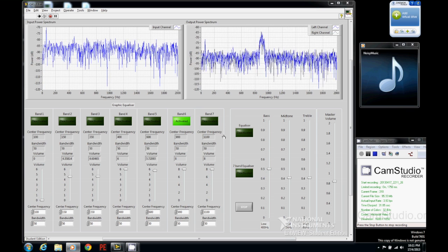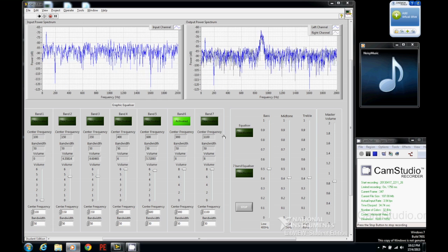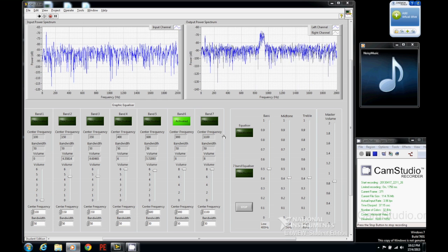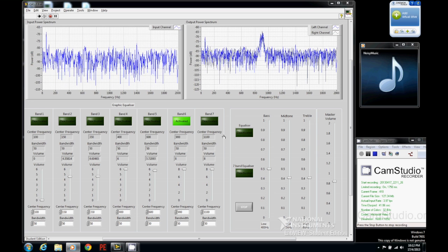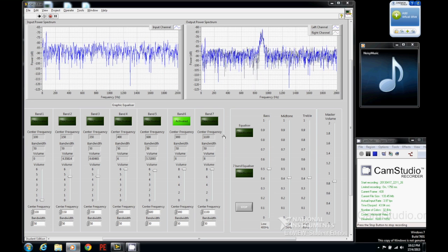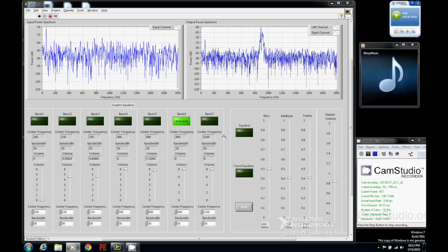Okay, we notice that the result is not significant because the frequency content in the 900 Hz band is not sufficient to mask out 1 kHz tones. Therefore, we try to utilize the higher frequency as masker. In this case, we use 1100 Hz, and here is the result.